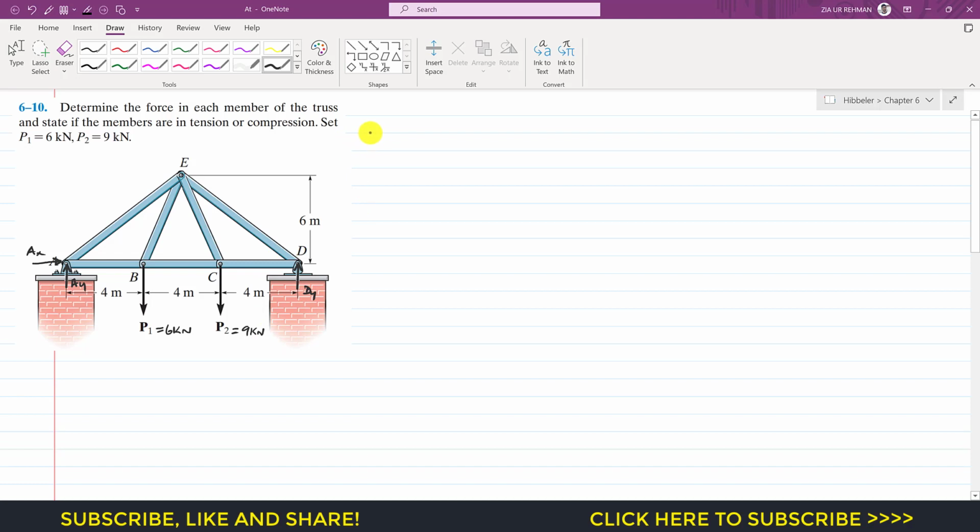So now to find these reactions, if I apply the summation of forces along x-axis equals 0, with this as my positive x and y-axis, we can see that there is only this AX support in the x direction, right? So this means that this AX is equal to 0. So this means that AX reaction is 0, so we need to remove it.